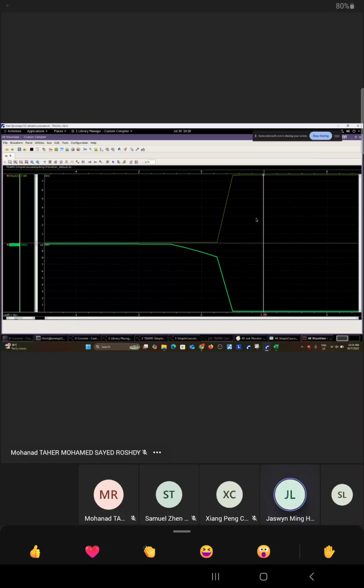So you can see that your maximum value for your V out is 7.6. Drag it all the way to your left. Then the minimum value that you can get for your V out is 24.3 nano. Makes sense, right? 24.3 nano means that it's almost close to 0. That's the ground. So in other words, your V out swing is actually limited by your power rail. Either 0 or somewhere slightly lower than VDD. Just now your VDD was how much? 10, right?